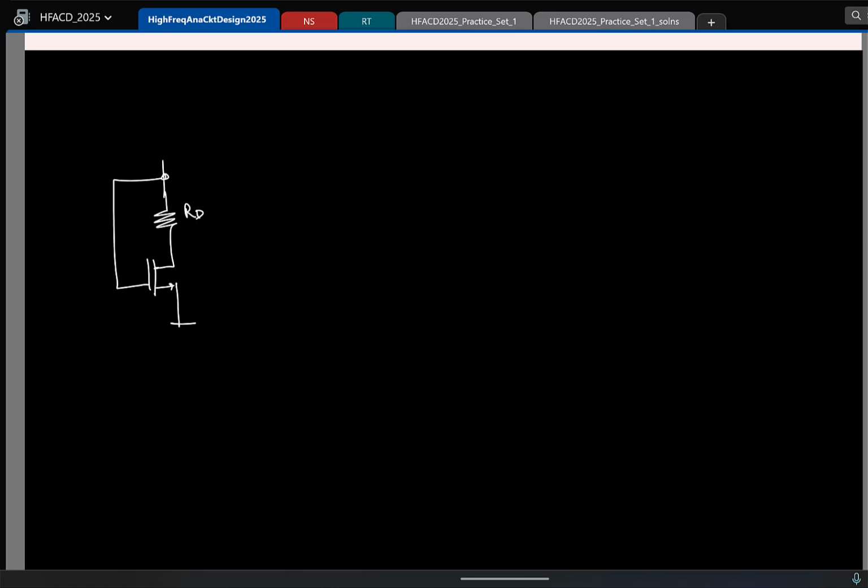So here you can ignore R naught. Let us say I don't consider R naught. To find the resistance, you apply a test voltage here. So this is also V test. What is the current? What is the resistance now? I apply a voltage V test. It seems like I draw current of Gm times V test. Resistance is? Right. So now at least you know if I don't have R naught, the resistance is 1 by Gm. That should be trivial.